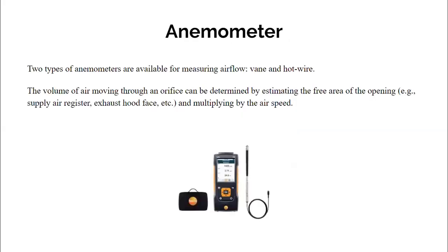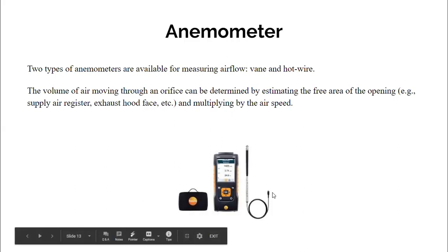This also is one of the instruments for doing the audit of compressed air systems, in which you measure the flow rate of the compressed air. And this is a simple principle. You use an orifice. The orifice would give you the flow rate by measuring the speed, and you know that flow rate is nothing but the product of cross-sectional area into velocity. So if you get the speed by using, you look at this, there's a probe,